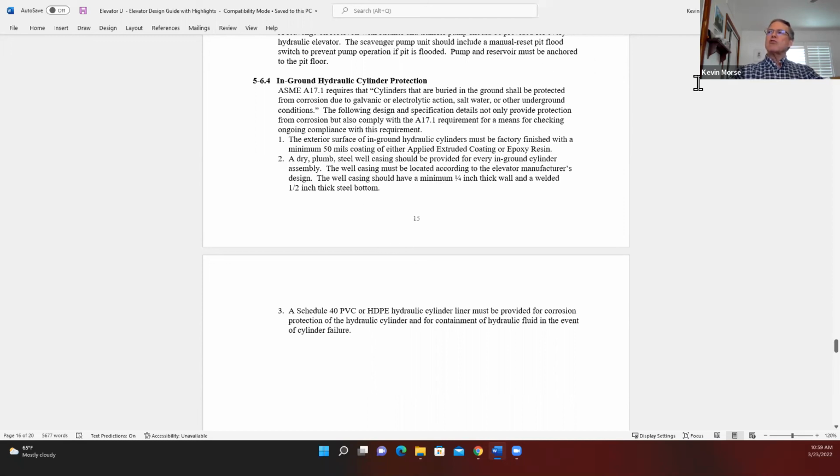Over years of contractors trying to seal the bottom of a drive casing that doesn't have a welded steel bottom, over time the concrete that they would drop down into the bottom of the casing to try and seal it would fail, and the drive casing would fill up with water. So that's why we went to a welded bottom on a steel drive casing.